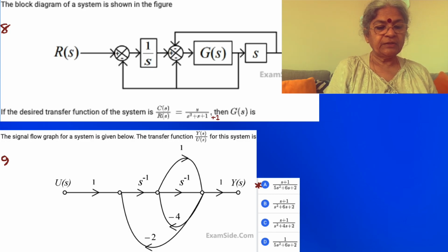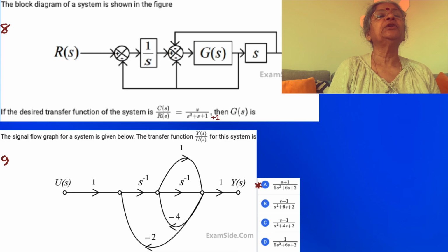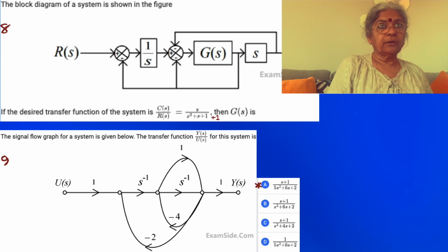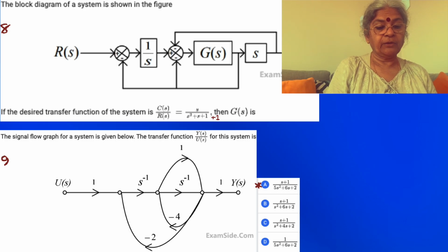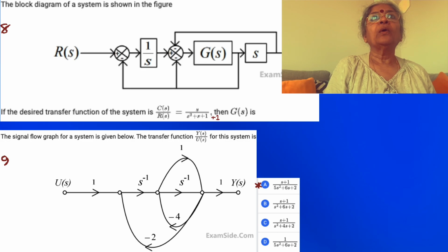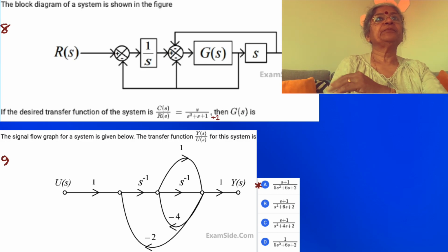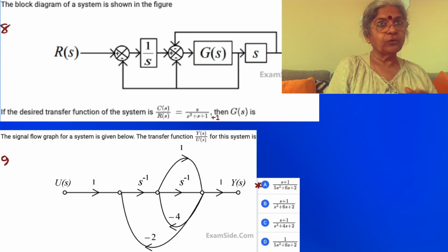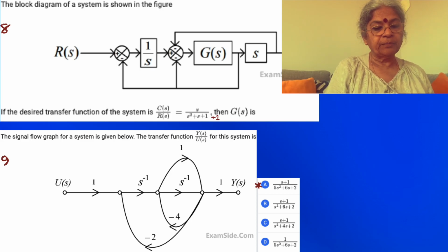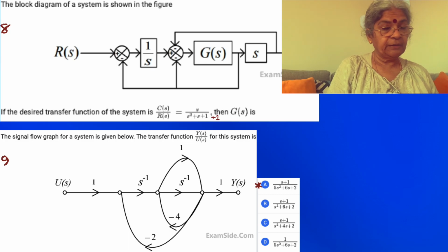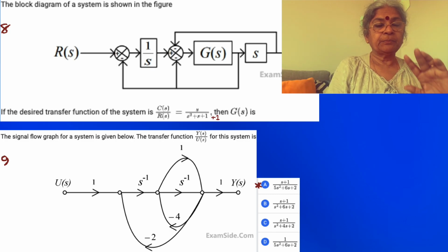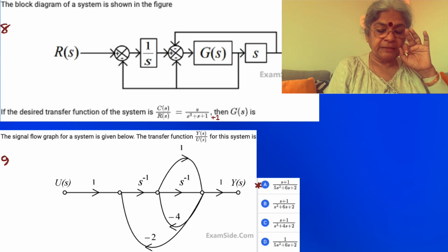Now let's start taking each of these feedback loops. Okay, so we see that we are having the first loop with 1 on the feed forward path and minus 4 on the feedback. So negative feedback is okay, and that gives us 4. Now we are having s square which has gone to the denominator, multiplying the 1 there, and also now we are having this 4 there. So plus 4, so 4 plus 1, 5 into s square. 1 because of 1 plus all the loops, so 1 is already there, and minus 4 into 1 has become plus 4 because of negative feedback. So we are having 4 plus 1, that's 5s square. So from amongst the answers, we see that A and D we have already neglected, so A is right. We are having 5s square, s plus 1 by 5s square. So far so good. Now we'll just simply check out the other loops.